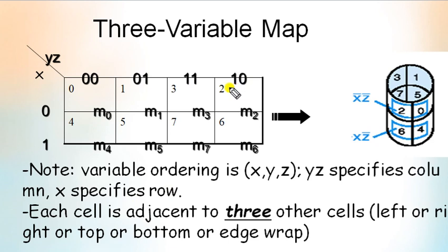What is the idea behind that? Because when we change a state, we should change only one bit from one state to another. When we write 1 0 here, there is a 2-bit difference between 0 1 and 1 0. That's why we put 1 1 before 1 0. Please note this statement: we will write 1 1 before 1 0 in the 3 variable Kmap.